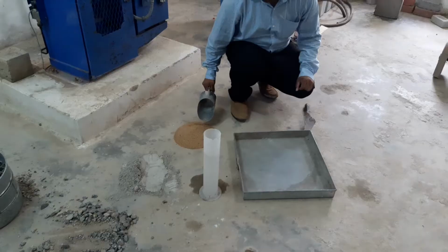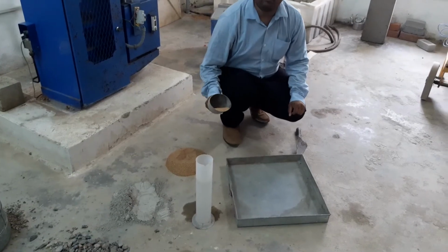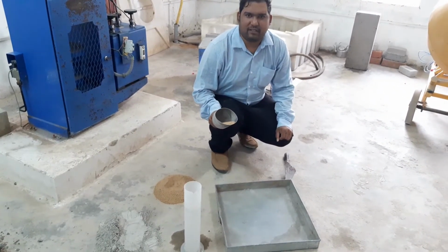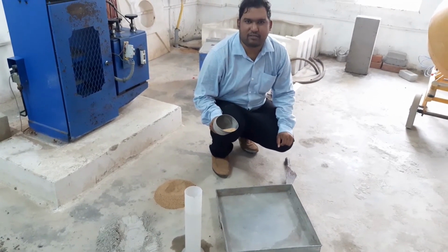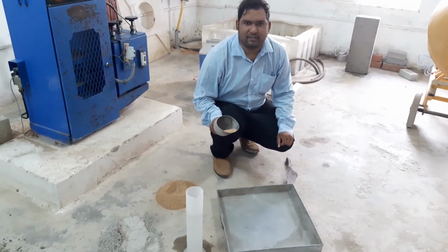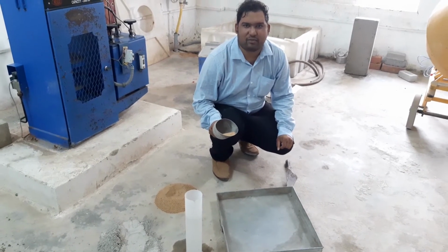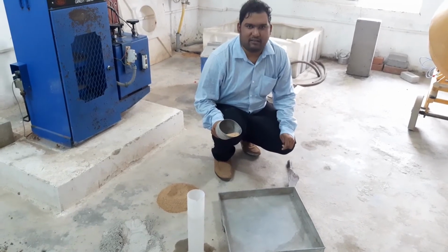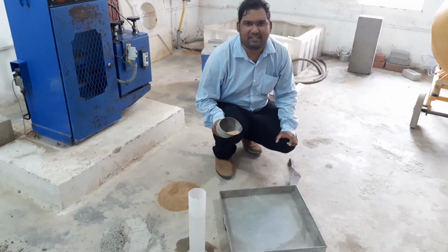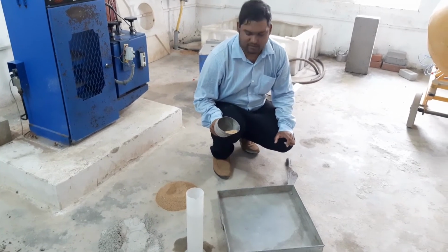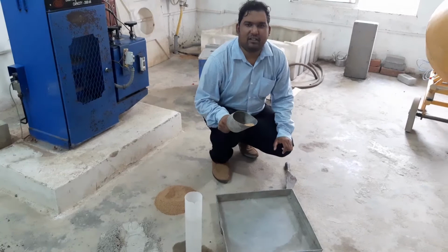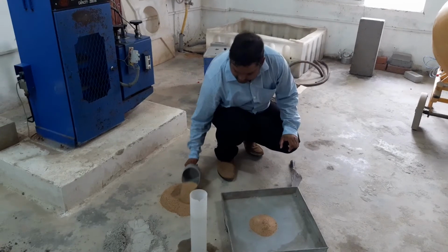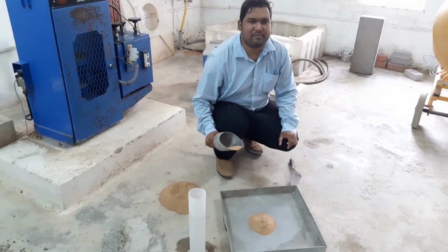So we will take some amount of sand. Suppose I am taking 50 kg of cement, as we have discussed earlier. The amount of sand should be 75 kg, but here we have not calculated yet what amount should be needed for our design. Now we are only focusing on the mixing procedure, how we are going to mix. So you will take the required amount of sand and you can put it in a non-porous mixing plate.